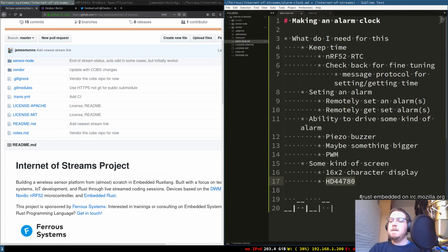You either drive it parallel, because the display itself is parallel, which means it takes like 8 or 12 or 16 pins to really drive this display. But the display doesn't have to be driven super fast. So what most people do is they put an I2C port expander on it, where they send these commands very slowly over I2C. And I say slowly, like 400 kilohertz, which is really not that slow. But if you only need to update the display 5 times a second or so, these port expanders let you control it with 2 pins instead of 12 or 16.